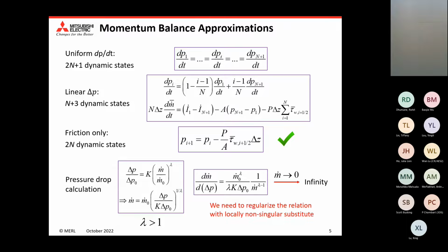And also, during the shutdown transients, I found that the time constant of compressor speed and fan speed should be carefully selected, otherwise the solution will fail. I think that because of the imbalance of heat transfer at the refrigerant and air side, that will blow up the refrigerant dynamics. Do you have a comment on that? Like, how fast should the fan speed also go to zero?